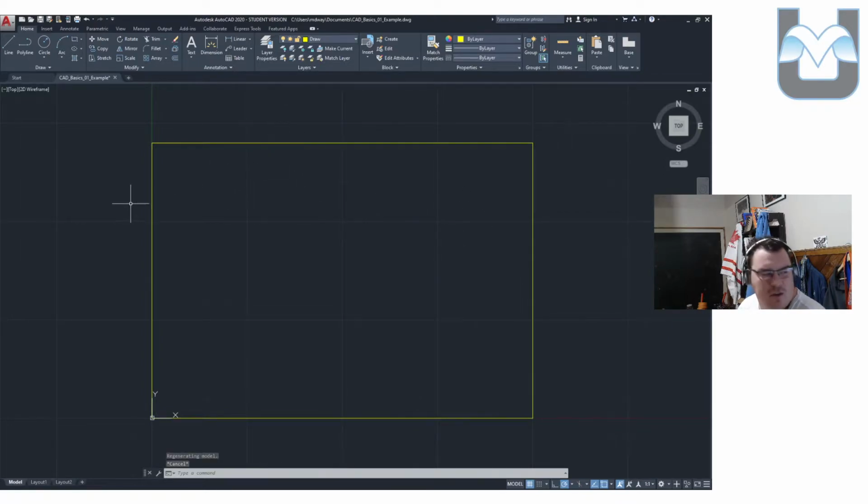So now in our drawing, we've got a line that I'm going to use the pre-2019 version that sits down here in the bottom left. The coordinates and the numbers are going to be slightly different if you're doing the post-2019 version, but the concept is there. I click on my line tool because I want to draw a line, and it says specify first point. In this case I've got point 2, 2, that's our starting point, and you'll notice that it now locks that end of the line to the point I just typed in.